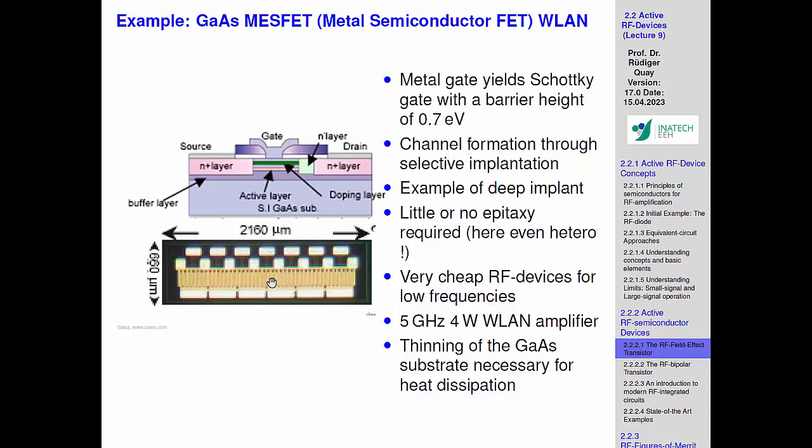The more parallel we have, the more difficult it is. And that's working against us when we go to higher frequencies, because then geometrically it's getting tighter. So the inductance also increases. Yeah, the inductance is one way. First of all, you have to keep the inductance down. And the second, because on this bus you have to connect it in some way, this line in itself forms an inductor. So that's a problem, which falsifies the phase.